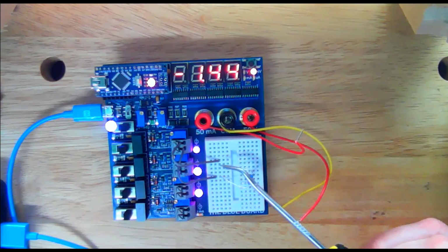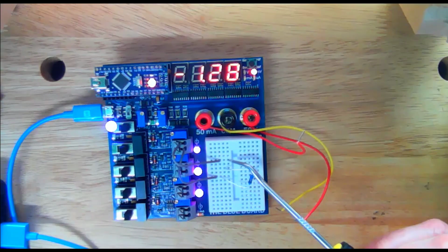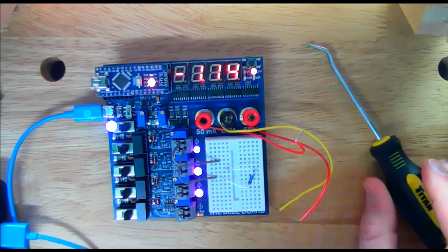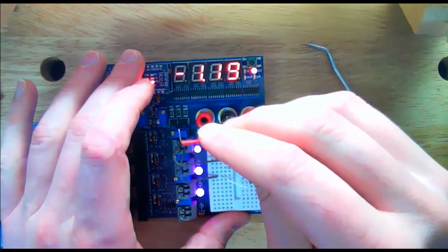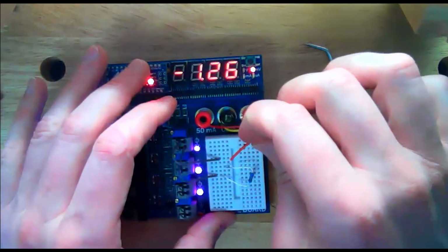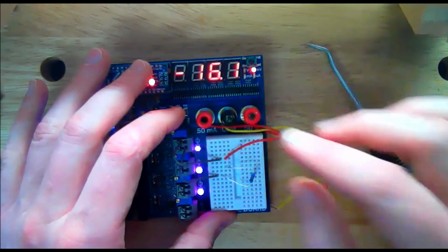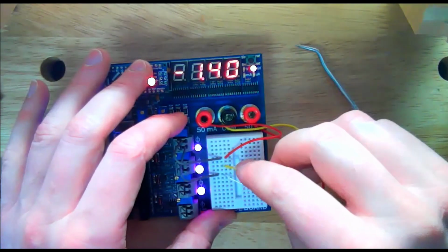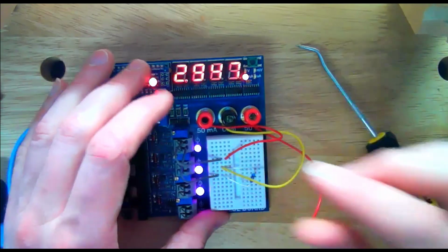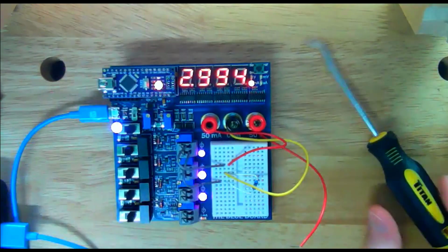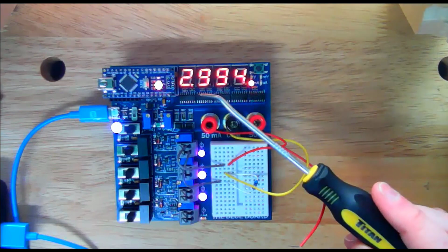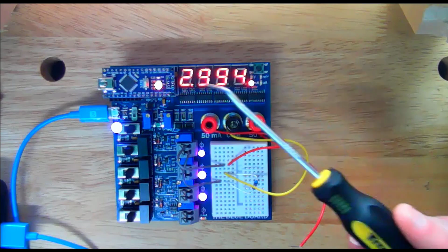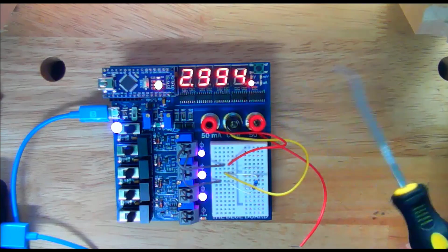So essentially, now I've broken the connection between the top side of the supply and the top of the resistor. And if I want to measure the current, I can connect the red terminal, 50 milliamp, to the positive side, and then my common terminal can be connected to the top of that resistor. So I broke the circuit, and now I'm forcing the circuit to flow through the current supply. And it looks like now I'm measuring, now you'll see the light change. Now the light that is illuminated is the milliamp light. It's showing 2.994 milliamps of current.